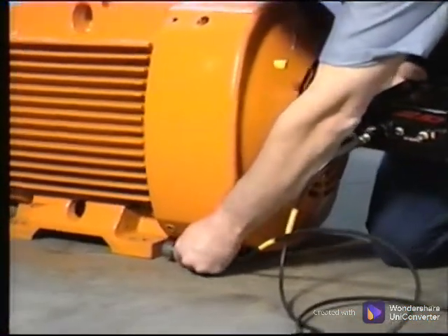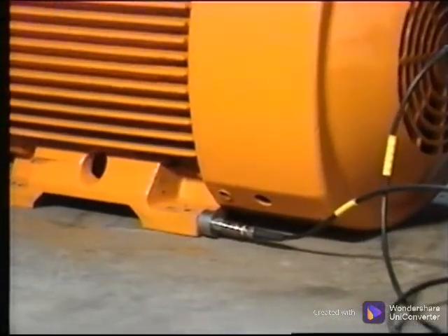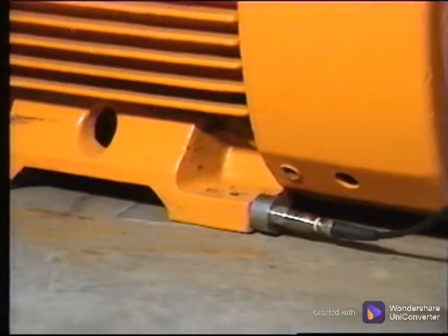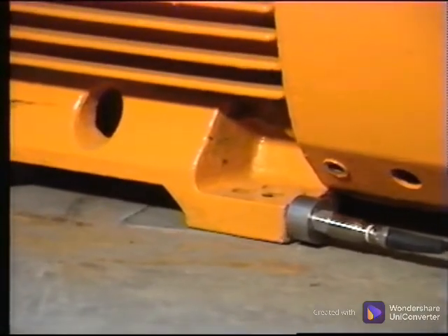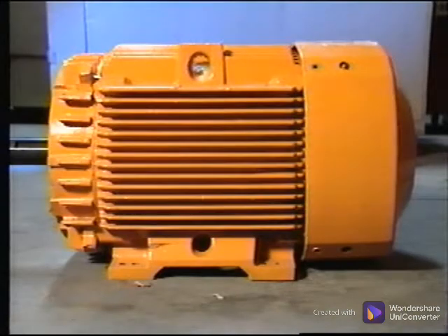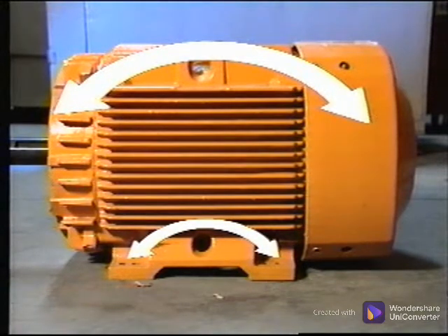The motor foot provides another location for the axial reading. If it is used for the axial measurement, the analyst needs to keep this in mind when analyzing the data. Because the foot is firmly fastened, any axial movement will be minimal. An axial reading on the lift hook would have more freedom to move and thus would have much higher levels of energy.